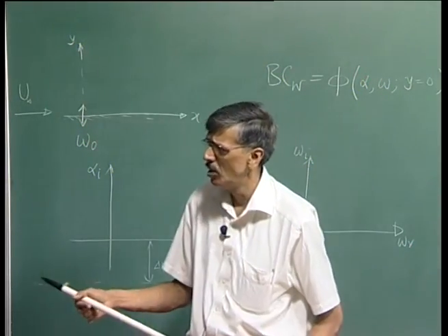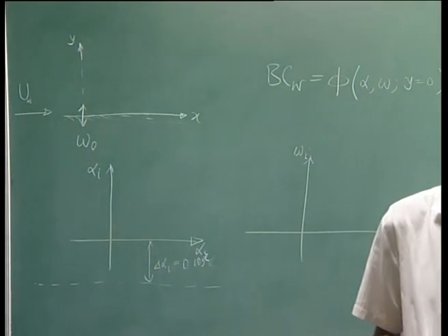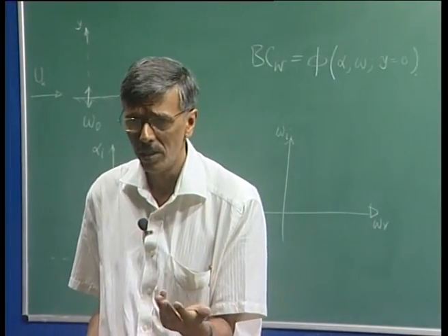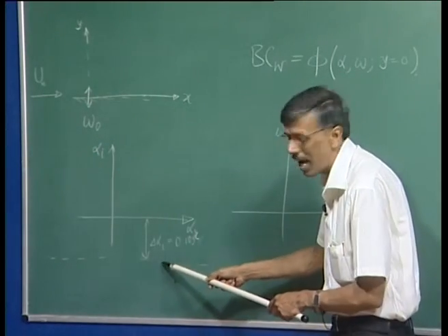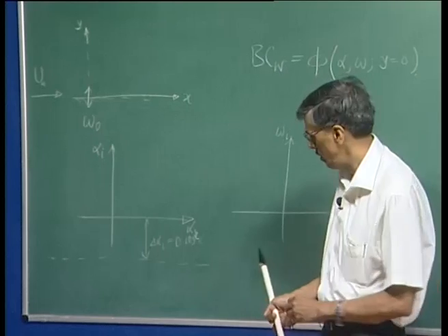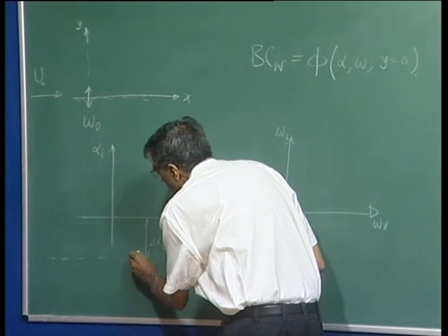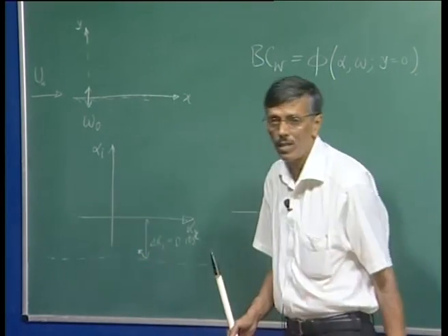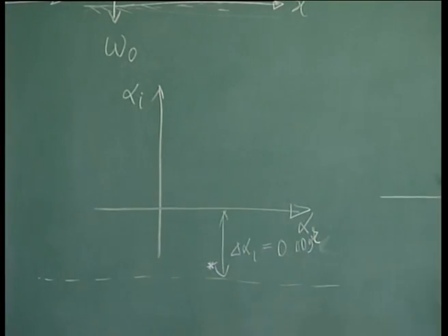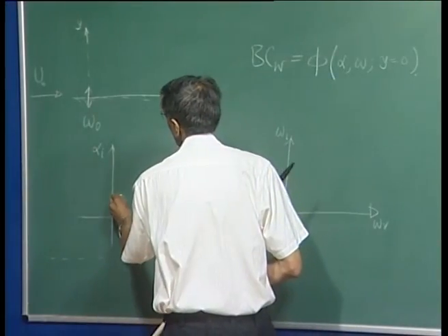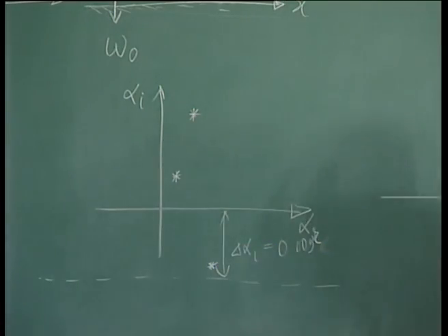Why are we doing it? For an obvious reason: for a Reynolds number of 1000, we see the maximum growth rate is of the order of minus 0.008. So, we wanted to keep it as close as possible, so there would be a maximum unstable mode somewhere here, and so we want to keep it like this. Now, what is the reason for it? You want to do it for the reason that there would be many modes. So, in this case maybe there are 2 modes in addition to this unstable mode.